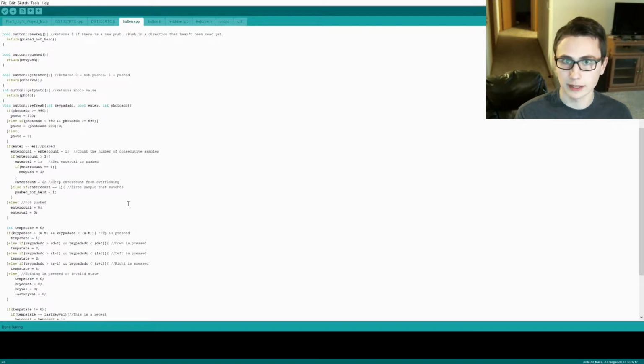when the averaging capacitor or debouncing capacitor is discharging through the 1 megohm resistor, there'll be times when the ADC counts reading will actually be a valid state, but not for long enough for the software debouncing to think that it was actually a button press.